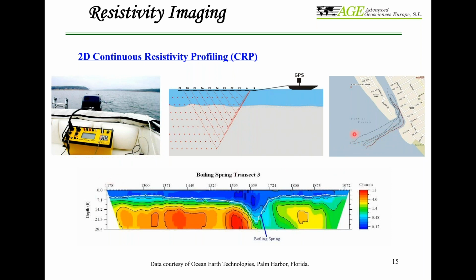That's why when you go turns and then keep measuring on the turns, or you can just stop measuring, and then let's say this is your survey area, okay? Or this is your survey area. So you measure here and then you just stop measurement and then you go all the way out and then come back. When the line is again straight line, start measuring, okay? You can do this kind of thing or keep measuring, and later on we have a software, Marine Log Manager software, to process the data and also just get a straight line this way.